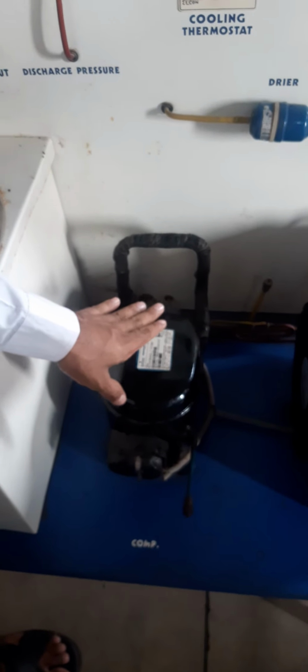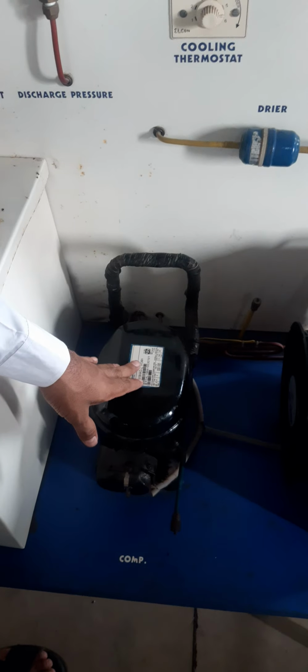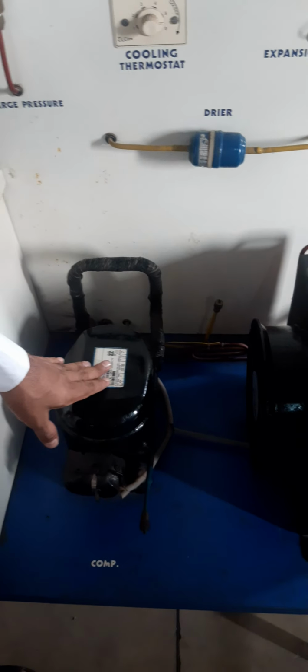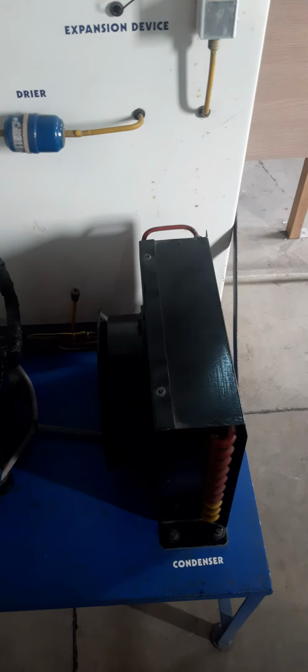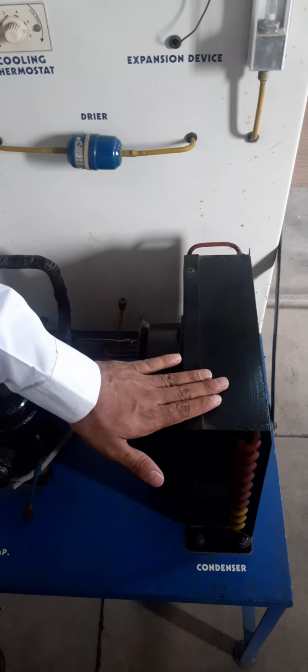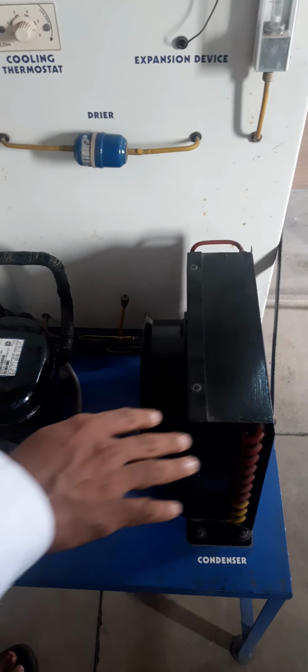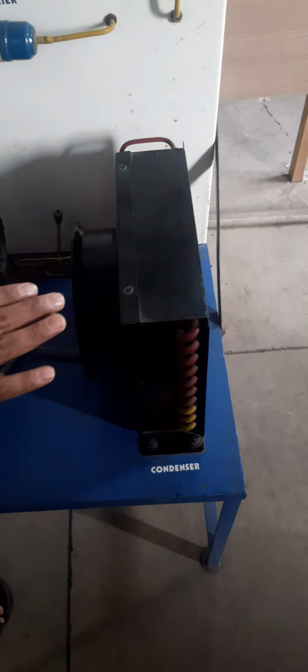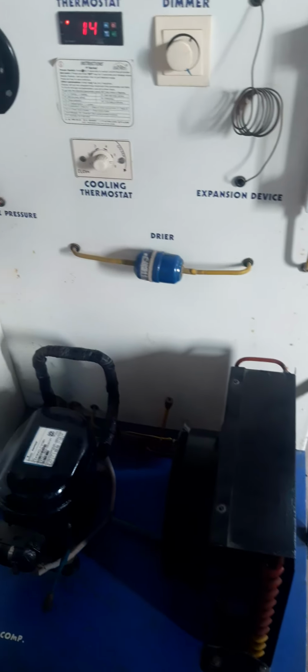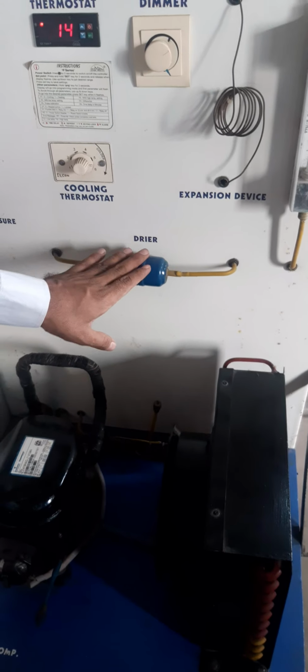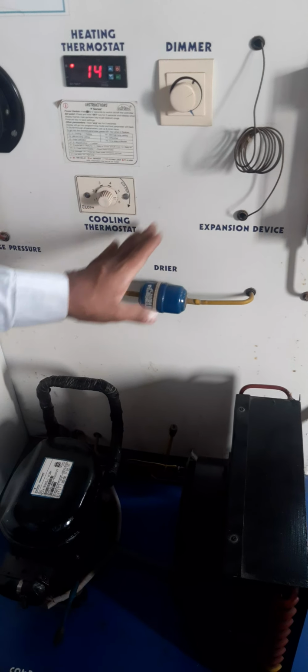You can see here this is the hermetically sealed compressor, where the temperature and pressure of the refrigerant increase from low pressure and low temperature. Then it becomes vapor. After that it enters the condenser, a forced convection air cooled condenser. Whenever it passes through this tube, the refrigerant is converted into a liquid. So the phase change takes place, and after that it enters the dryer. Here again the temperature and pressure of the refrigerant are high, and finally it enters